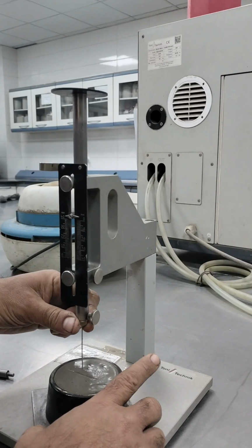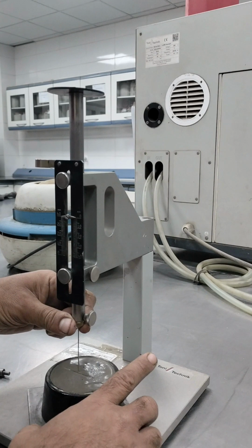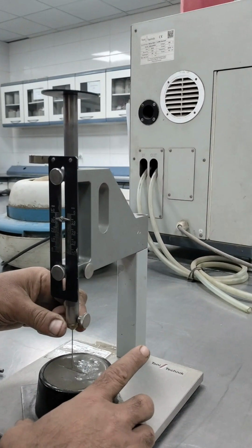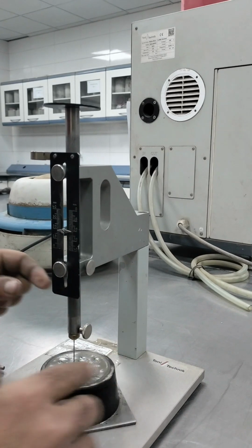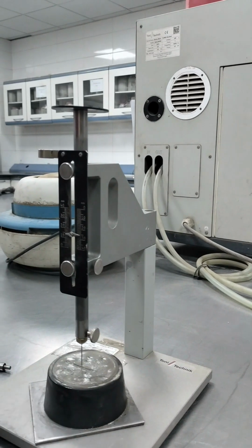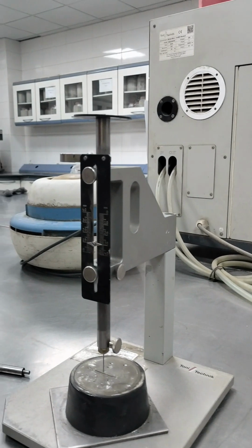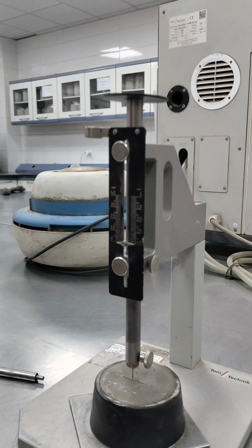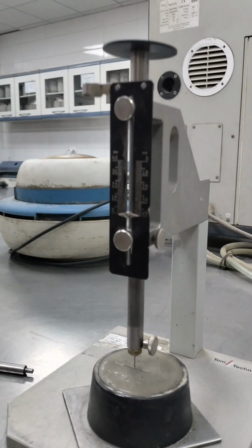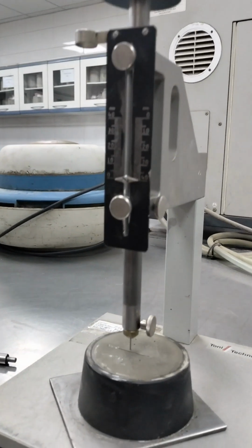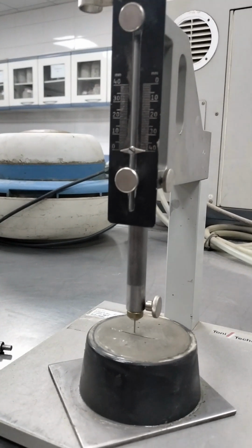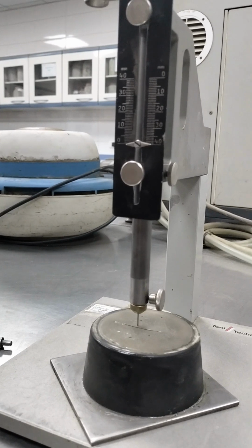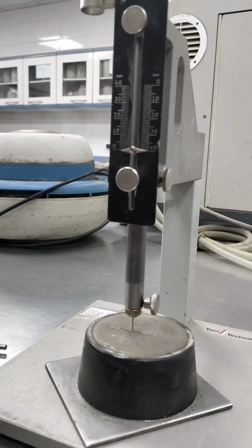After a suitable time, position the mold, base plate and container under the needle of the Vicat apparatus. Lower the needle gently until it is in contact with the paste. Pause in that position for between 1s and 2s in order to avoid initial velocity or forced acceleration of the moving parts. Then release the moving parts quickly and allow the needle to penetrate vertically into the paste. Read the scale when penetration has ceased, or 30s after the release of the needle.